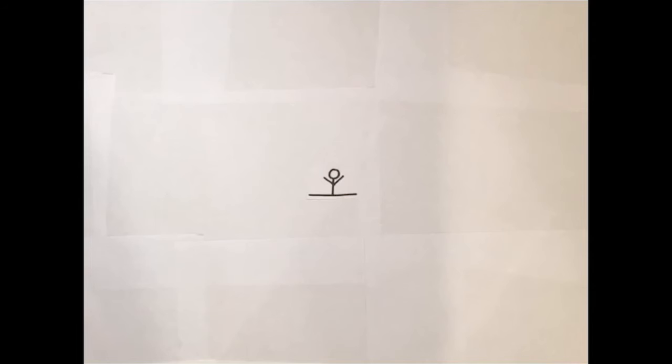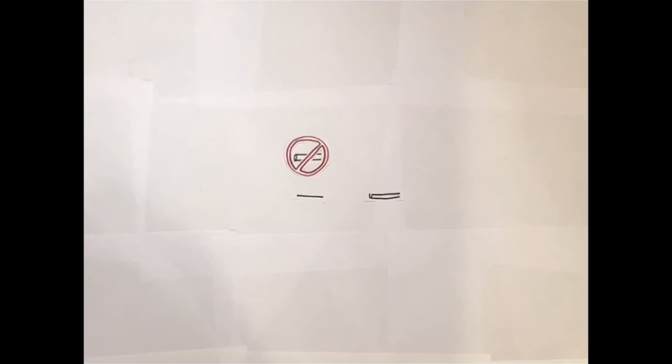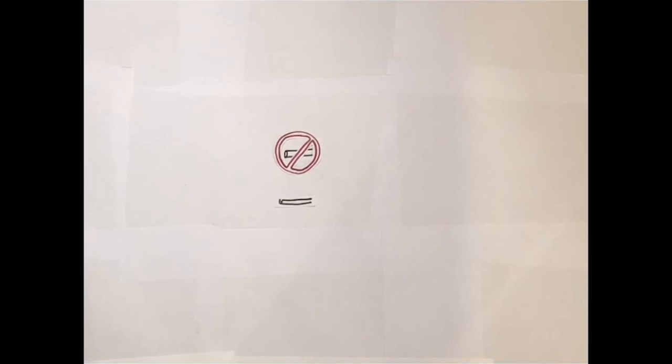It is very flexible in management and is directly compatible with any battery storage. 48 volts is chosen and it's considered as low voltage, so it is very safe to handle. Even if you accidentally touch a live terminal, it won't harm. This also allows them to use relatively small diameter cables, so they are less expensive and they are physically easier to install.